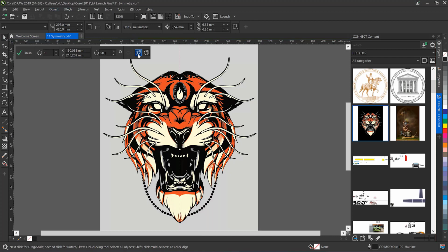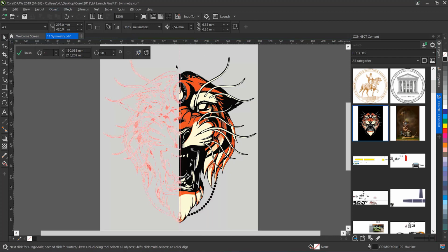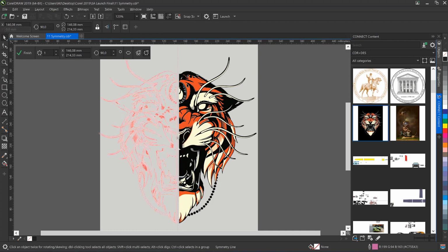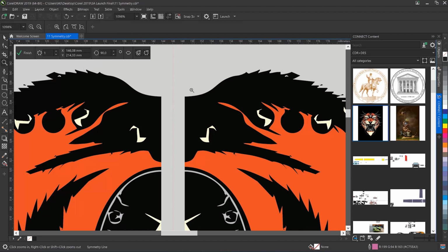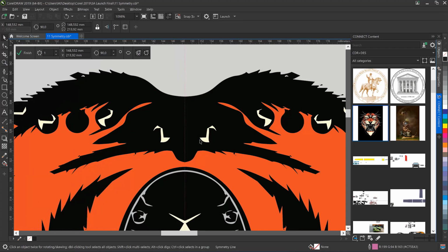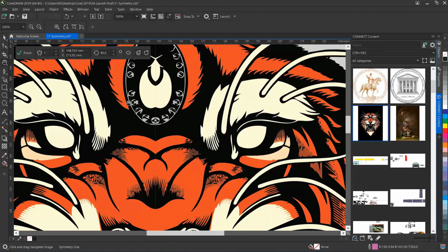Corel has created a pretty convincing bilateral symmetry. By turning off Show Full Preview on the Properties bar for the symmetry, we can see that we're slightly out in terms of alignment. Let's turn it on again and it becomes more obvious. By making sure that we have the Show Symmetry lines visible, that's the last button on that property bar, we're able to get a perfect alignment. So it's simply click and drag. That's looking good. Let's explore how easy it is to create symmetry objects.